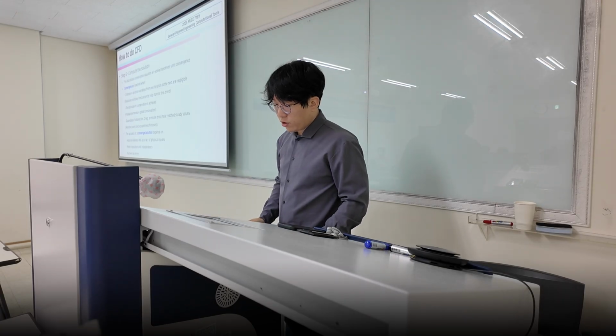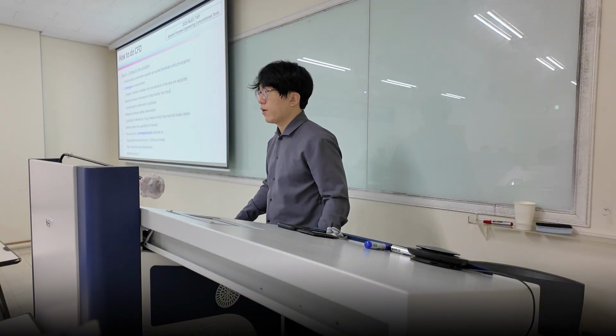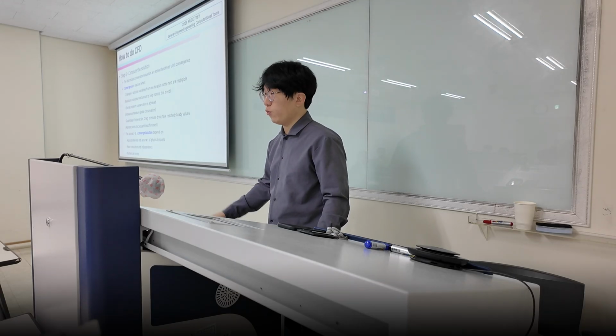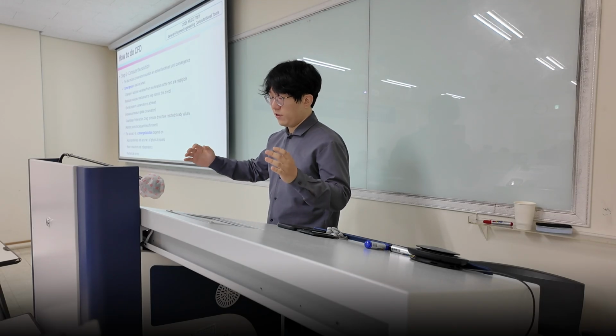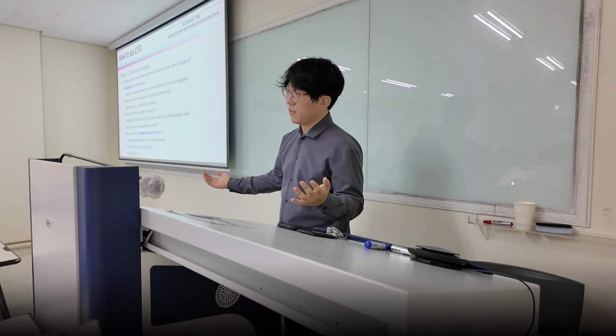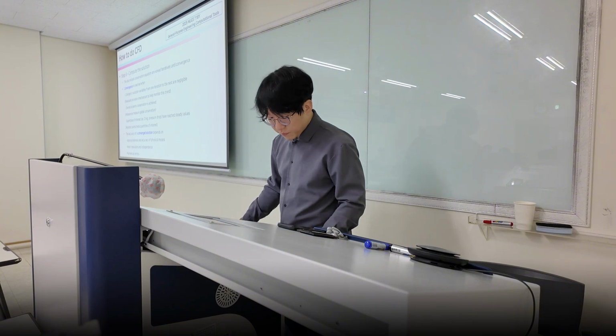And you're gonna compute the solution. One term you have to remember here is convergence. When you get a numerical error, we don't really say we got an error. We say we have a diverging solution, meaning we don't have one set of solution. We have numerous, infinite number of solutions, or we just have NaNs everywhere.